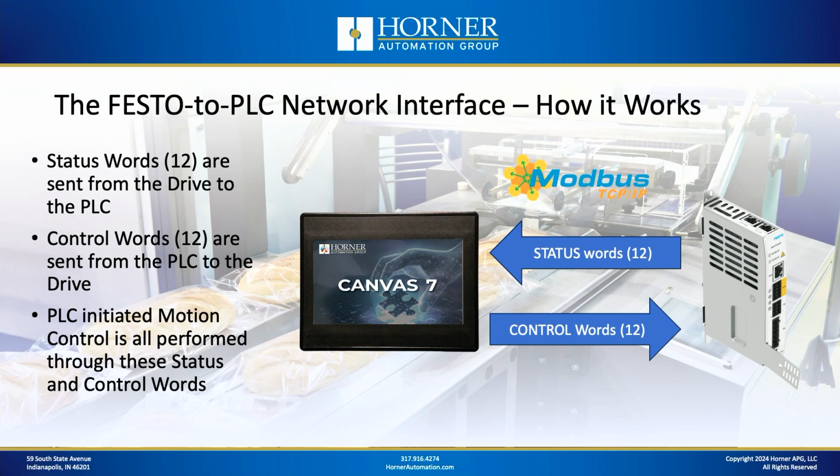Okay, so how does the actual motion control work between the Horner OCS and the Festo drive? Well, it really works the same way as it would with any PLC. The Horner OCS is acting as the PLC here. You've got 12 words of data going each direction at high speed over an Ethernet connection between the drive and the Horner OCS. You've got 12 words of status coming from the drive to the OCS, and you've got 12 words of control going from the OCS to the drive.